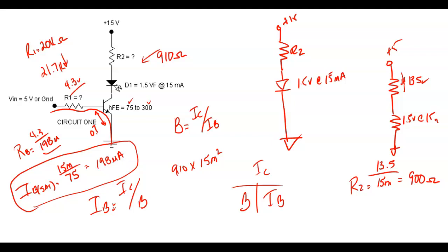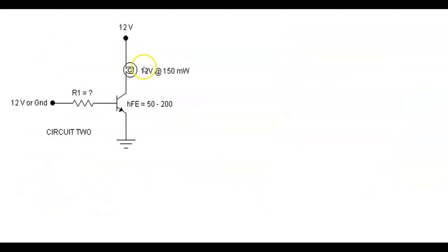So we assume it's a 0. So if my load is dropping less than what I've got up here, then you'll have to use a series dropping resistor. If it's rated at the same, like light bulbs, there's all types of 12 volt light bulbs out there. That's what your car light bulbs are rated at, right?